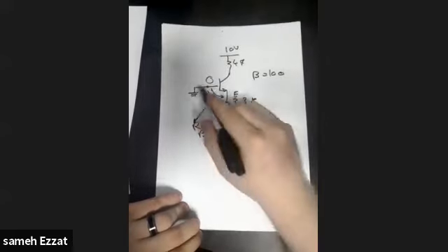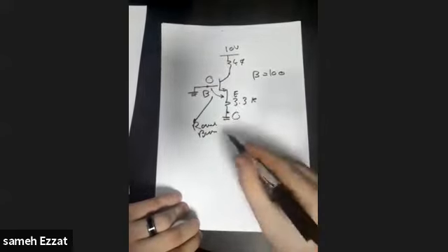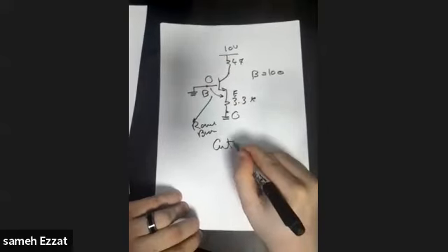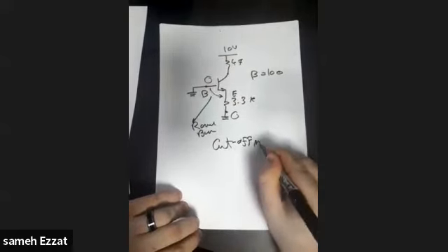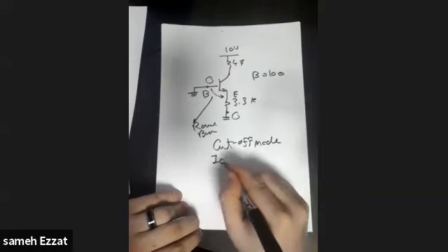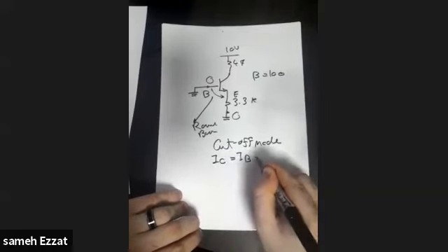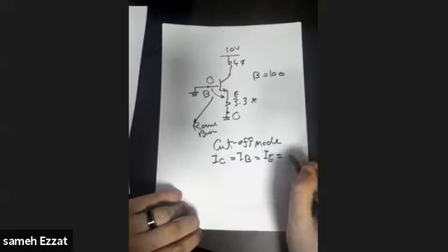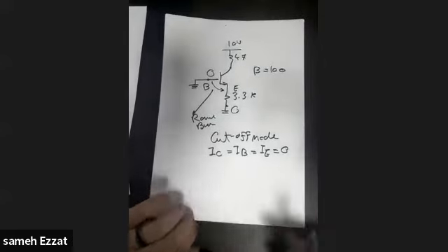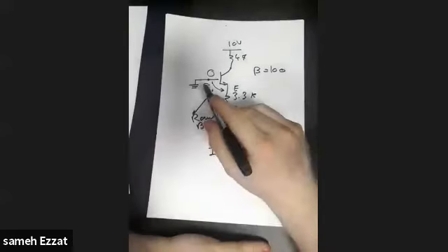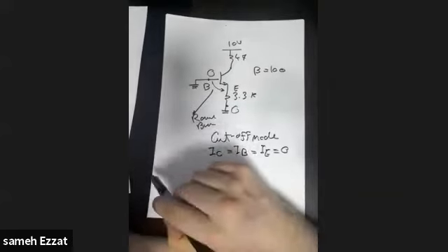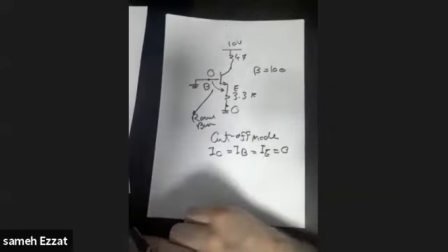So whenever you find that this is a reverse, then it's a cutoff mode, which means that IC equal IB equal IE equals 0. No current will move in the BJT as far as this base emitter junction is not in the forward bias.